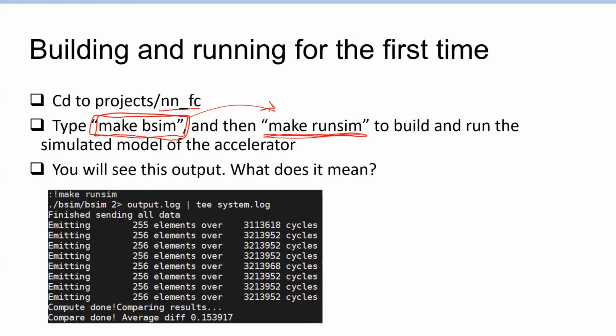One thing to bear in mind is that the simulator, because it is a simulator, uses software to simulate what would exactly happen cycle by cycle inside the resulting hardware. So the wall clock time that it takes for the software simulator to execute, how long your simulation runs, has absolutely nothing to do with how fast your resulting hardware is.